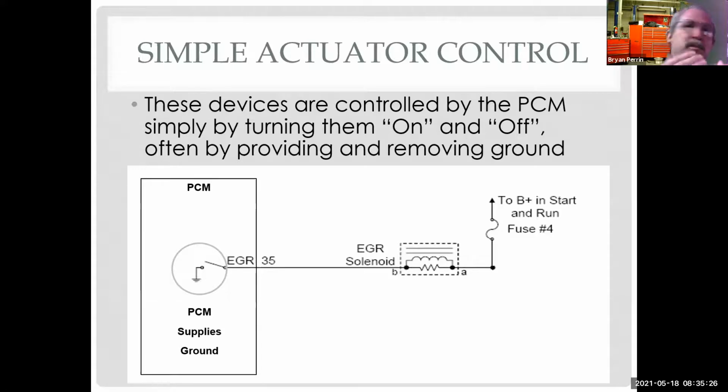So I probably want to use some longer leads that might allow me to back probe at the A and B connector and bring those leads into the passenger compartment with me. And then I could look at a meter. But if I'm looking at the meter, looking for something to happen, it's kind of hard to drive, isn't it? Again, probably not the best idea. So why don't I replace the meter with a scope? Because a scope's going to tell me if it goes high and low, doesn't it? That I could prove that the circuit is working electrically.